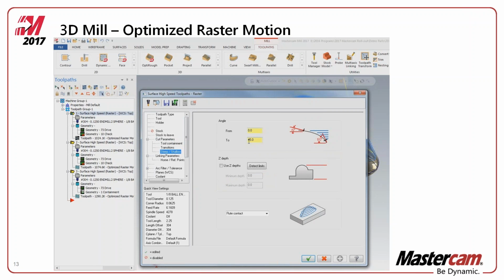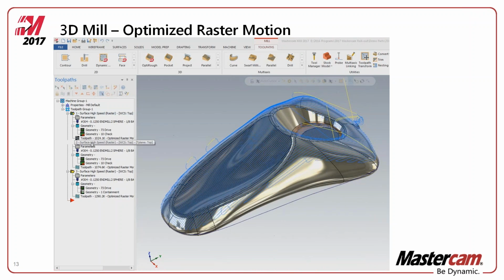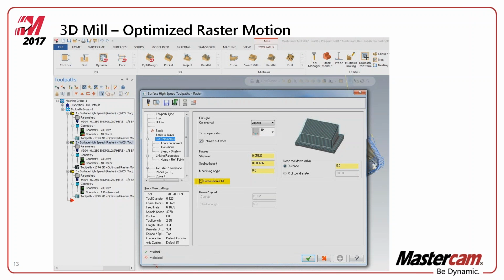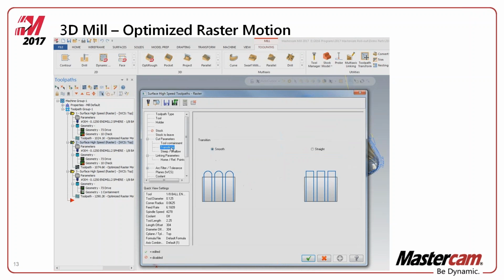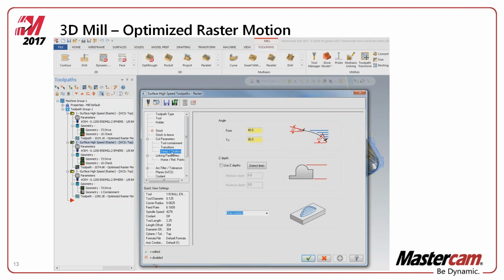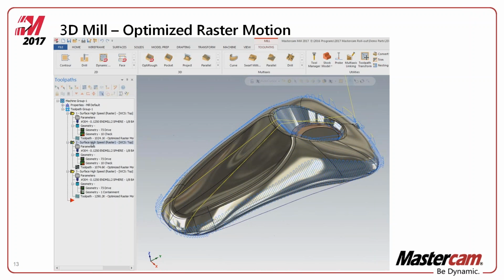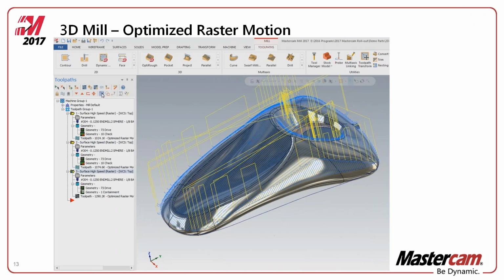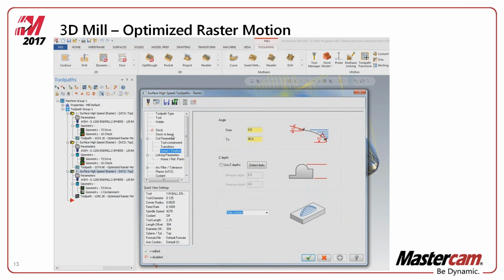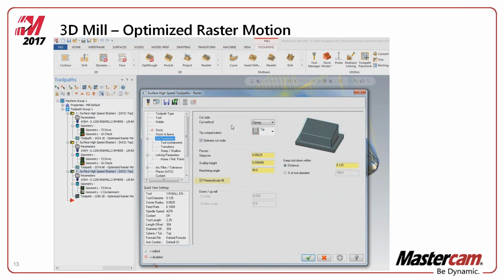You can see the toolpaths. What I have set up is anything from 0 degrees to 45 degrees is going to be one motion, and then of course I can come into the perpendicular fill, turn that on, and do basically from 45 to 90 degrees as well here. So a couple ways we can base that toolpath, or the third one I had set up here is where we're going to do everything together from 0 degrees to 90 degrees with the perpendicular fill on.